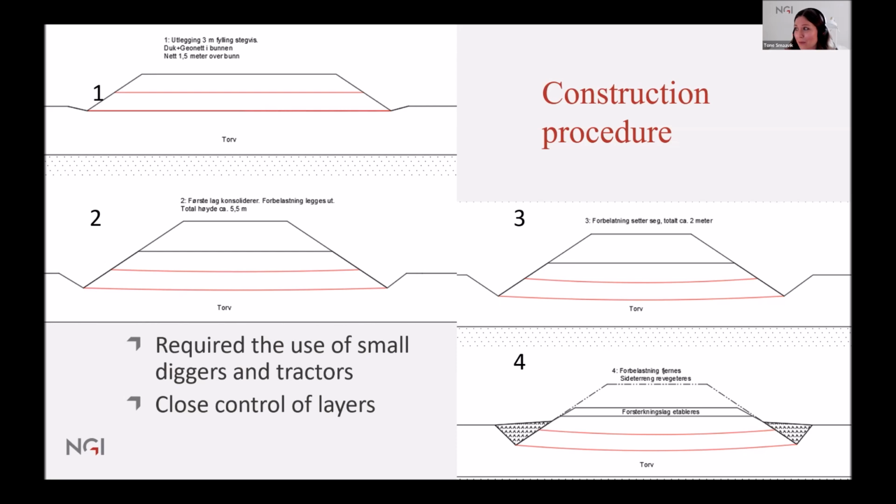So what they did, we've then put a 2-meter extra fill on top to progress the settlements that we're expecting, because we're expecting about 2 meters of settlements in this material, and we don't want to build our road before most of the settlements finished. So this is to be left in place, and when we have achieved the settlements that we've predicted, then you can remove your surcharge fill and establish your road. And the surcharge fill can also be reused within the project, so moved further along the line of the road.